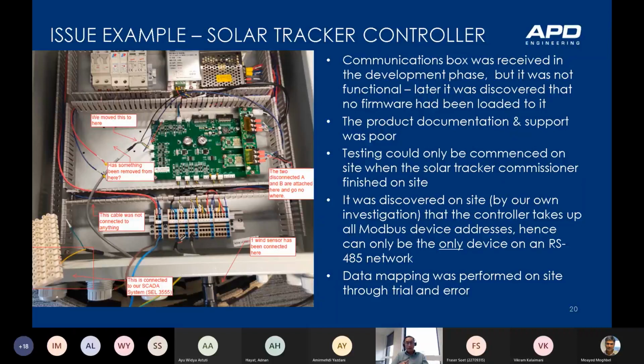It was discovered on site by our own investigation that the controller takes up all of the Modbus addresses, hence it can only be the only device on an RS485 network. We had designed it so that it wasn't the only device. I'll show you just the slide after this, but we had to actually do all this on site, which causes further delays. Data mapping was performed on site through a bit of R&D, trial and error.